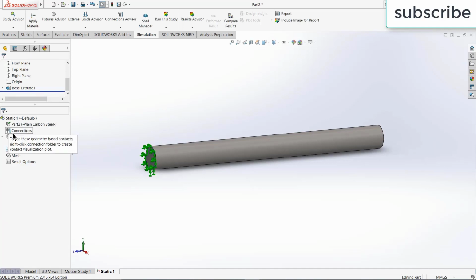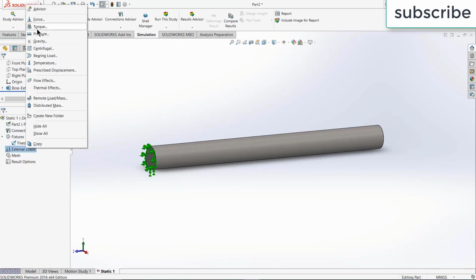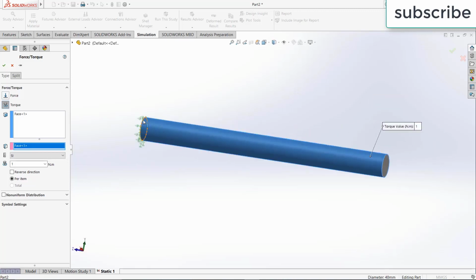Click OK. Now right click on external loads. As I told you, I am interested in torque. So select the torque, select this face. Now it is asking for an axis or cylindrical face. You can select this face again, but here you will see that it is selecting the whole shaft. But I just want to put a load at this particular, for example, a small strip of area. So how can I do that?